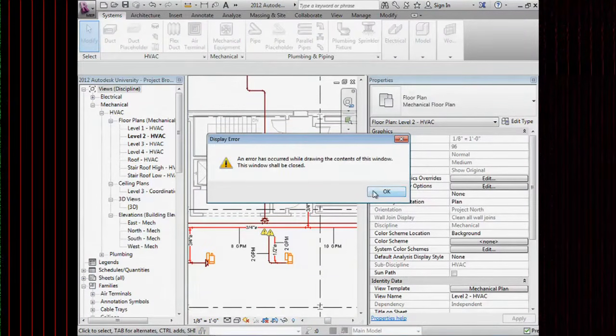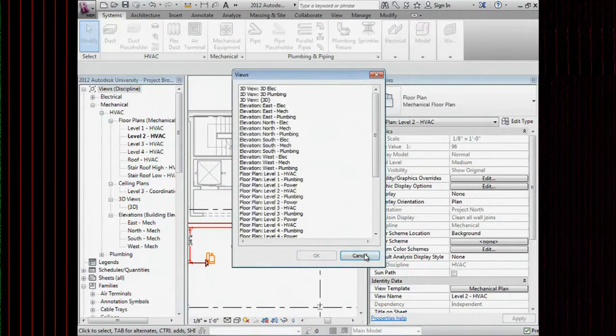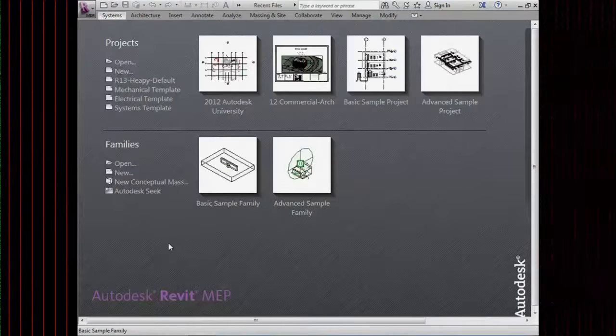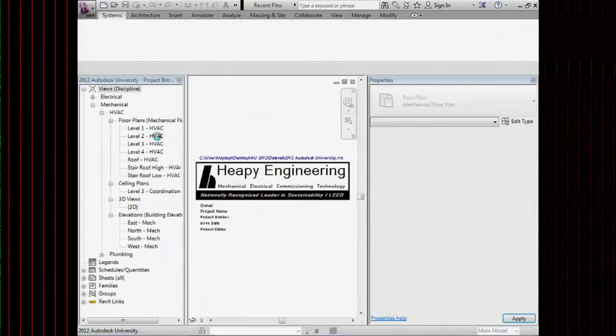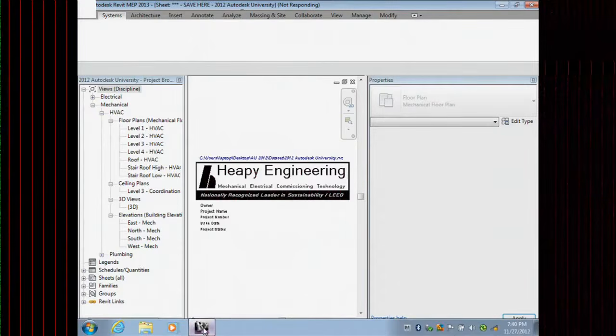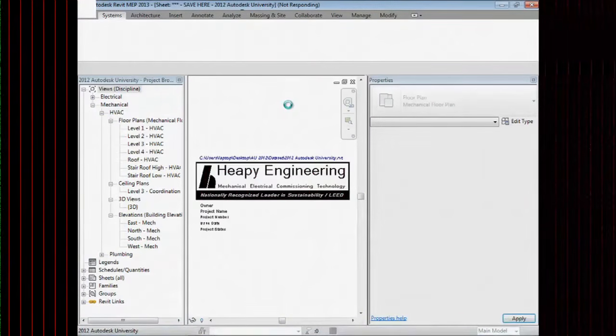Real quickly, in regards to the project that I referenced with the 400 sanitary systems, our plumbing department went back, took our recommendations after the project went out, and cleaned up their model. They said by the time they reconnected everything, it dropped the total number of systems down to like 5 or 6, which is where they should have been. They basically agreed that it was their mistake that the performance of the model was not where it was supposed to be. So understand that this does have significant impact, especially if you're dealing with 400 or 500 systems in your project.